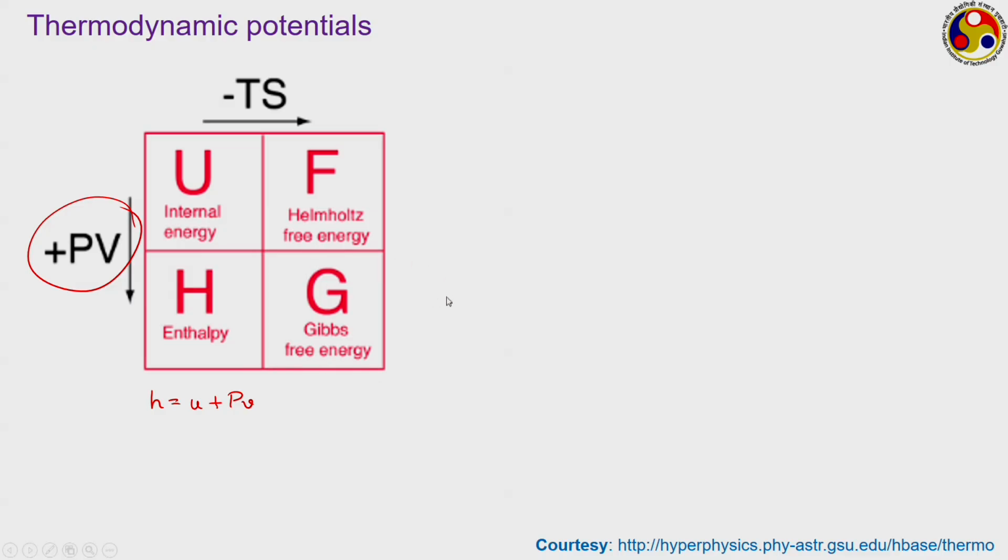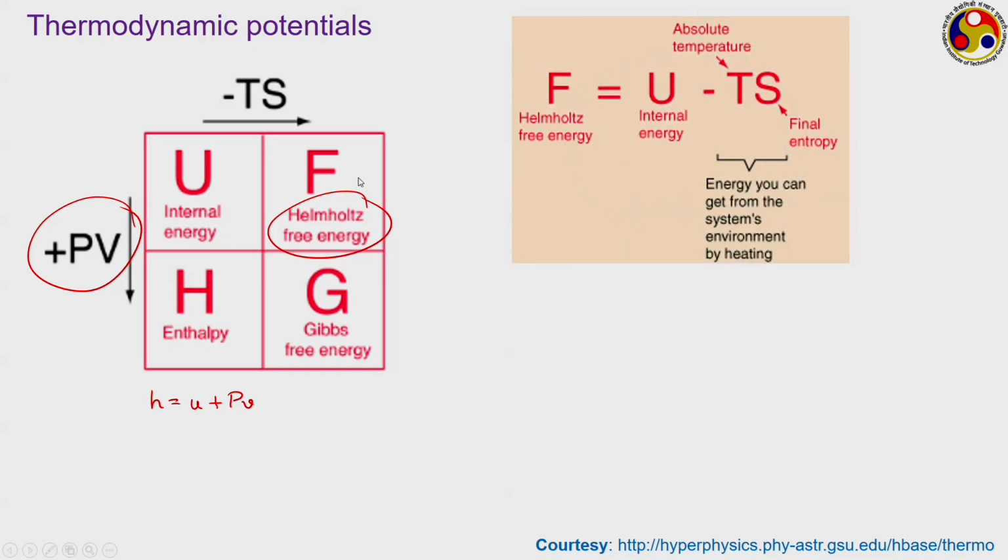That is called the Helmholtz free energy. As shown here, it is a Helmholtz free energy and it is represented as U minus Ts. Just follow these symbols. Once we subtract Ts from this internal energy we get this Helmholtz free energy. Or in intensive sense, if we write, small f is equal to small u minus T into small s. In certain textbooks a symbol small a is also used, like the book that we are mostly following in this course, the book of Cengel and Boles, that actually uses small a as a symbol.